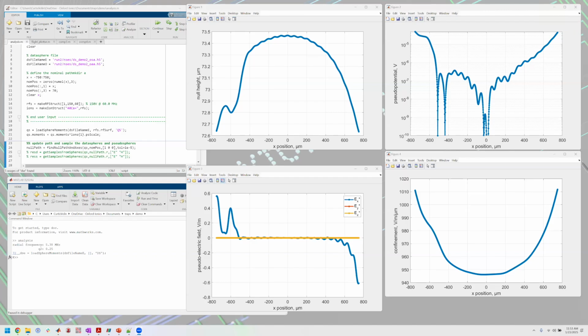So an electrostatic solver, of course, cannot estimate what that would be. We're only dealing with perfect conductors, and in the static regime, you would have to use HFSS or potentially Nullspace EM to simulate that sort of thing. For the regime of traps that I've designed, those kinds of simulations show that there really isn't phase lag. Perhaps you could design a trap so bad that it actually had that phase lag, but that's up to you.